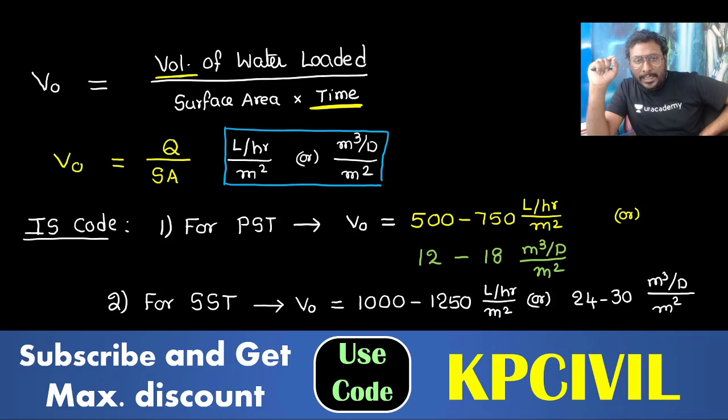So for the primary sedimentation tank, V0 is 12 to 18 meter cube per day per meter square, and for the secondary sedimentation tank, V0 is 1000 to 1250 liter per hour per meter square.